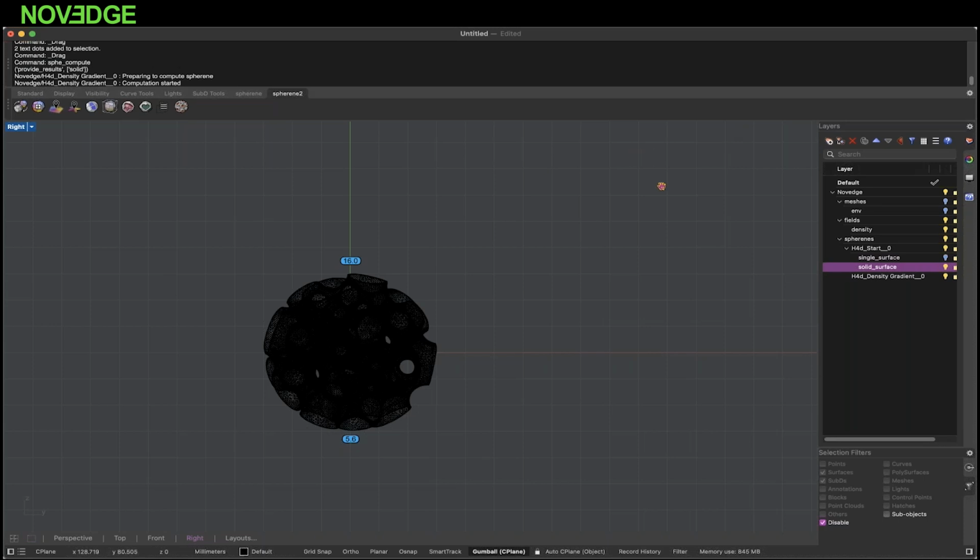In the meantime, what would happen if we want to change the wall thickness from left to right? Okay, let's press this button and add a field point for the thickness, add 1 point here, add another point here, and change this one to 2 millimeters.